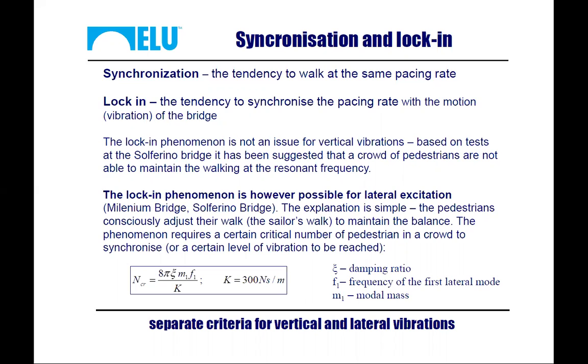But then we have also another phenomenon, which is called the lock-in phenomenon. And lock-in could be defined as the tendency to synchronize the pacing rate with the motion of the bridge. So one is synchronization in itself, tendency to walk at the same pacing rate, regardless of what that pacing rate might be. Another thing is the tendency to synchronize that pacing rate with the motion vibration of the bridge.